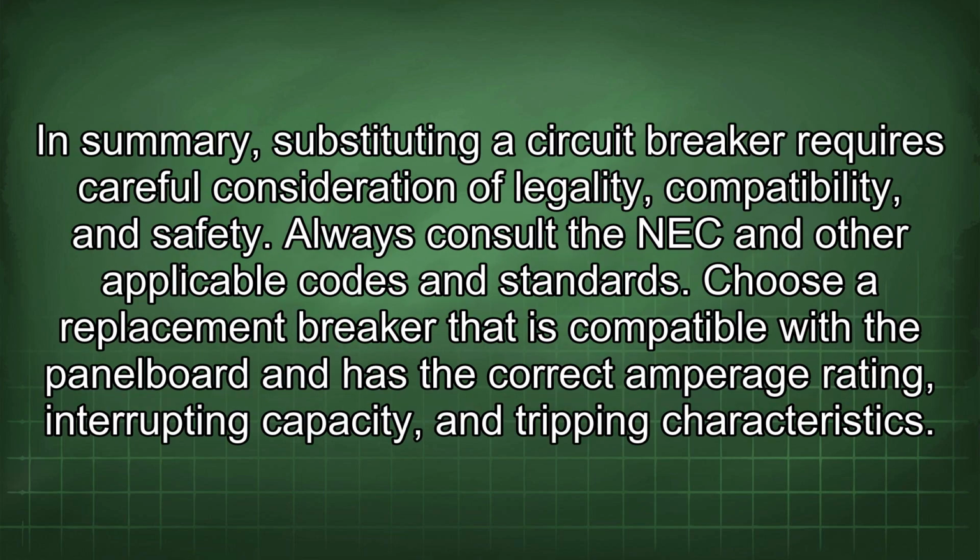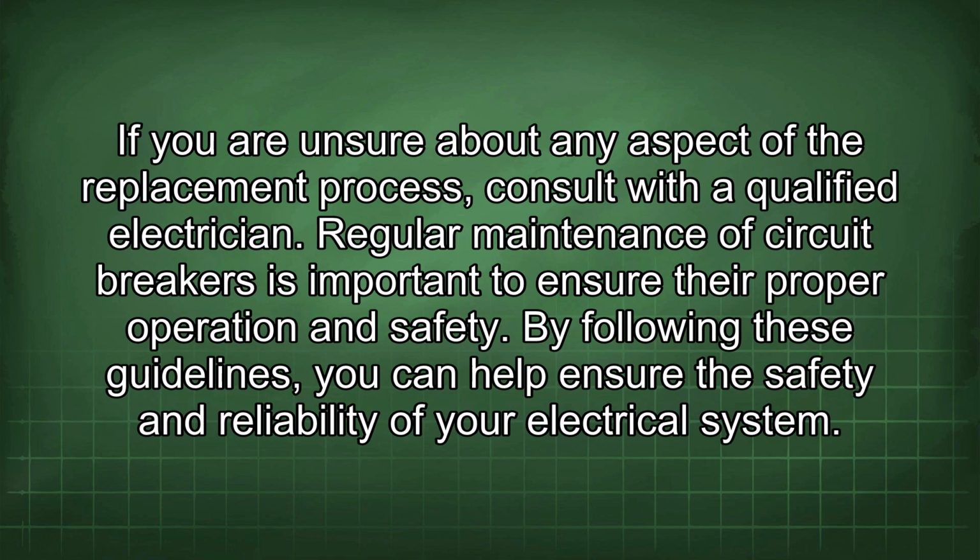In summary, substituting a circuit breaker requires careful consideration of legality, compatibility, and safety. Always consult the NEC and other applicable codes and standards. Choose a replacement breaker that is compatible with the panel board and has the correct amperage rating, interrupting capacity, and tripping characteristics. If you are unsure about any aspect of the replacement process, consult with a qualified electrician. Regular maintenance of circuit breakers is important to ensure their proper operation and safety. By following these guidelines, you can help ensure the safety and reliability of your electrical system.